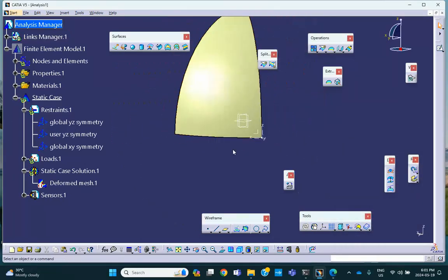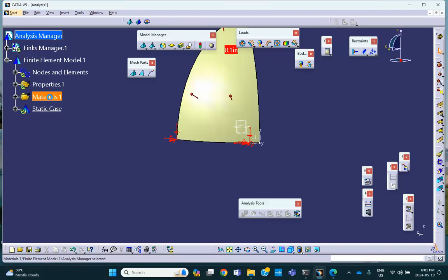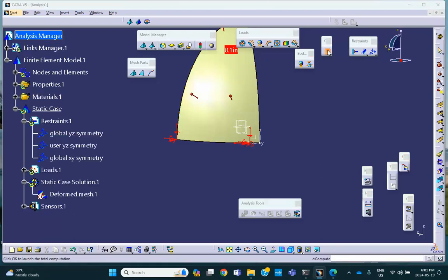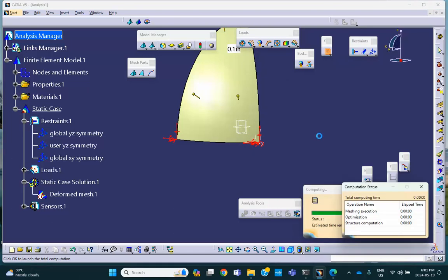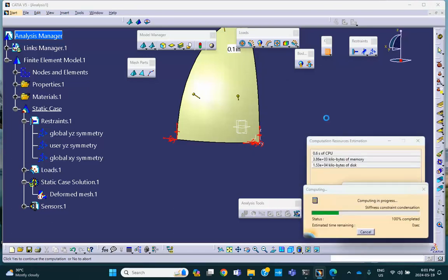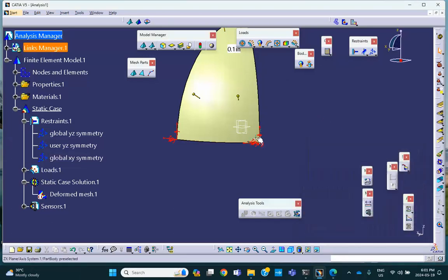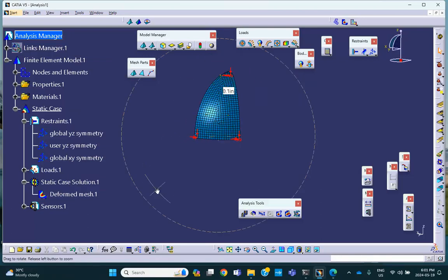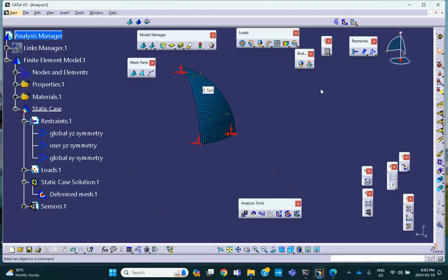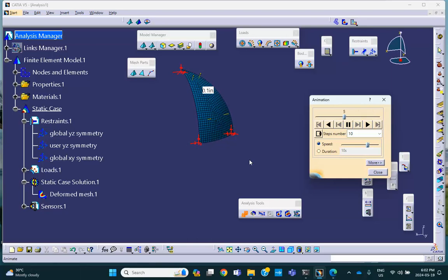Now we go back and run it. It's going to be exactly like we expect. Okay, so let's try to run it now. You know what happened? I created the geometry by revolving by 40 degrees, but the coordinate system that I wanted to create here was rotated by 45 degrees. Now, when I plot this, it better be perfectly inflating. Okay, so let's go here. There we are. That's what happened.